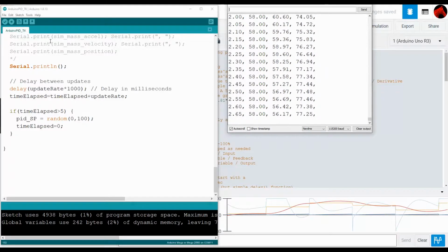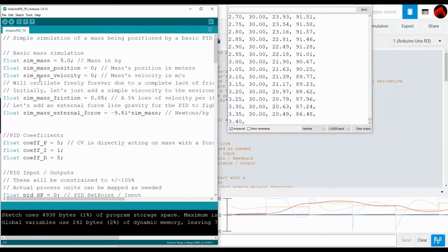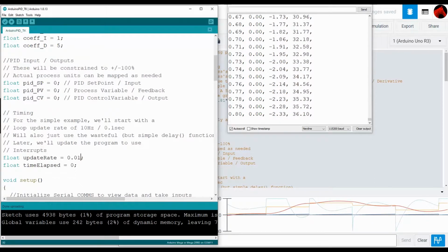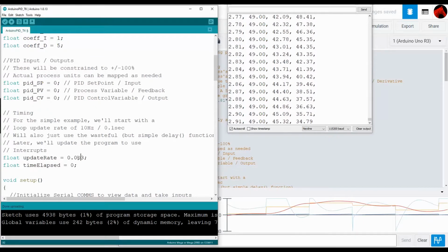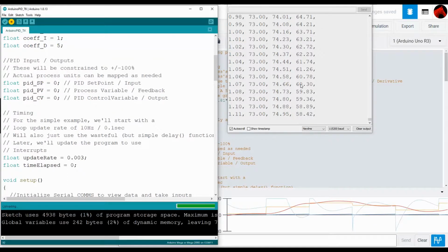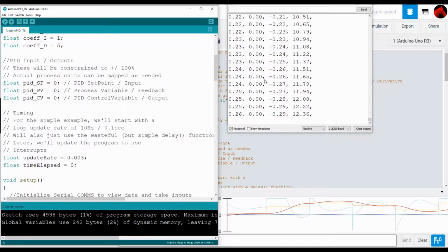And the Arduino can definitely run faster than this if we change the update rate to be 100 times a second. The timestamp is still keeping up well. 300-ish times per second. There will be limitations because we're currently printing out data to the serial console on every iteration. The serial communications can definitely cause lags.